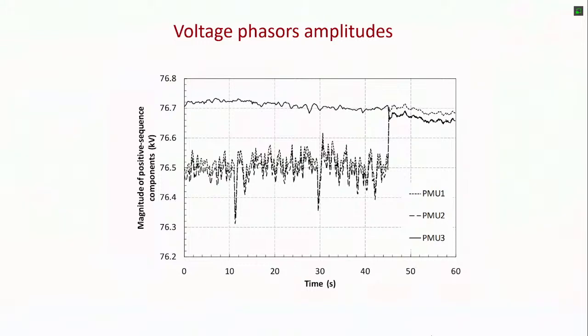So they have the same voltage. But if you open the circuit breaker and this part of the network is in an island condition, this voltage has a frequency that is different from the voltage in the network. So there is a condition in which the voltages at the terminals of the circuit breaker are in opposition. In general, the circuit breaker can sustain the double rated voltage, but one of the old circuit breakers did not succeed. So there was a flash in the circuit breaker in the substation.